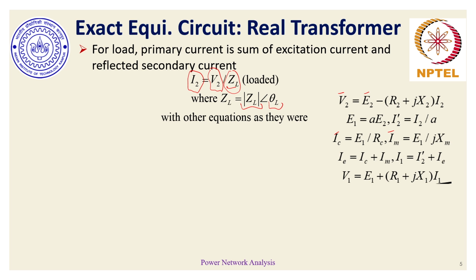Now, one clear way of approaching and drawing the phasor diagram would be to start with the relevant equations which are going to remain the same no matter whether the transformer is loaded or unloaded. One of the important equations which remain invariant would be the relationship between the induced EMFs on the primary and secondary, which is defined by the corresponding turn ratio.